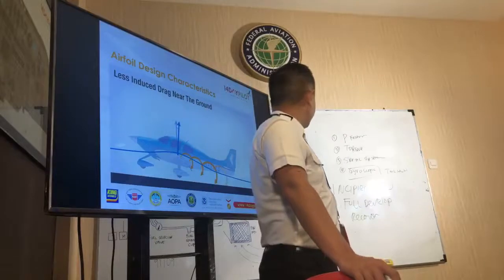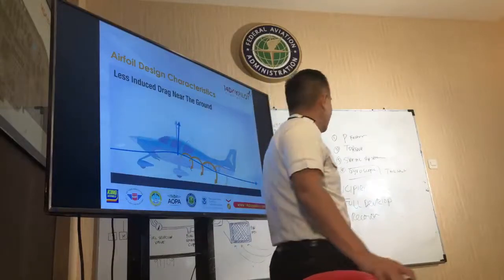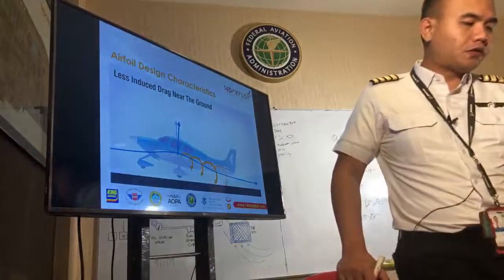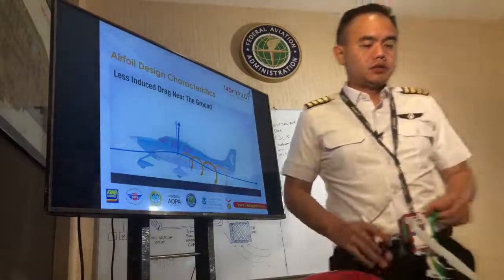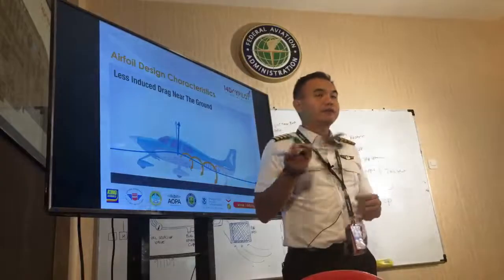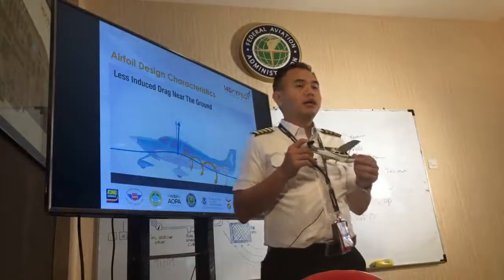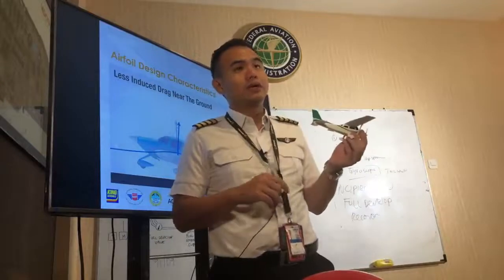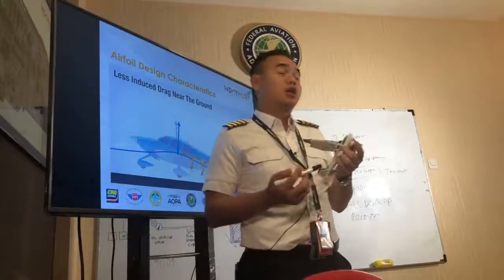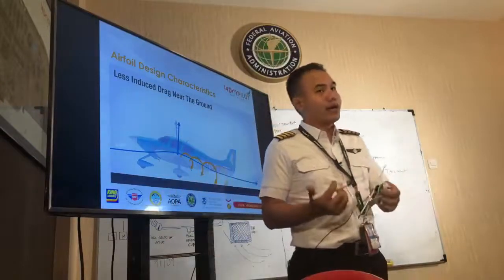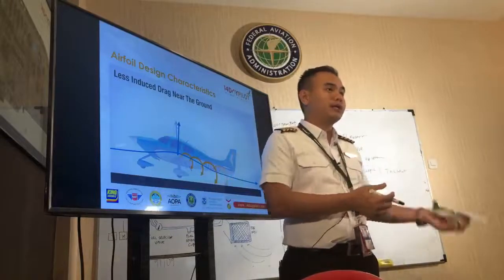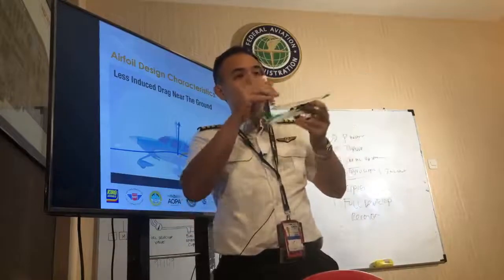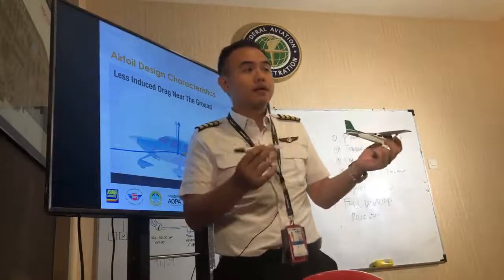Let's talk about stability. Oh, one more thing. The four forces, to maintain straight and level: lift equals weight, thrust equals drag. Lift will never equal drag or thrust. Lift, weight, thrust, drag.